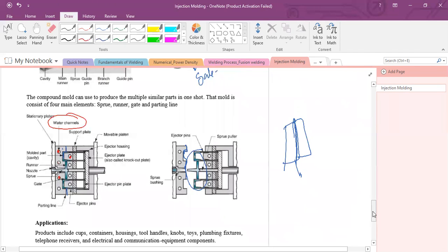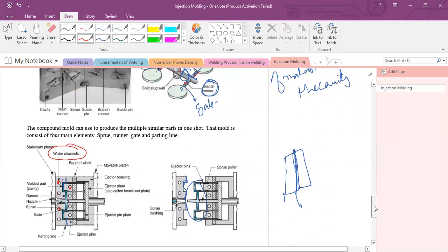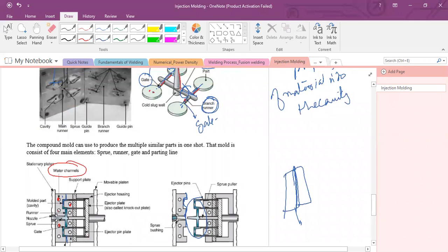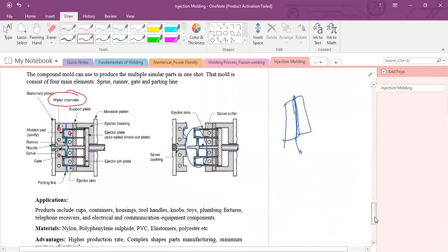The mold can crack, or porosity will be created inside the part. Porosity means small pockets can be created due to high temperature. Due to high temperature, we can get extra melting, and we don't require extra melting. We require proper and optimum melting during injection molding.